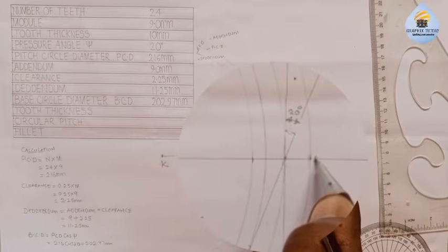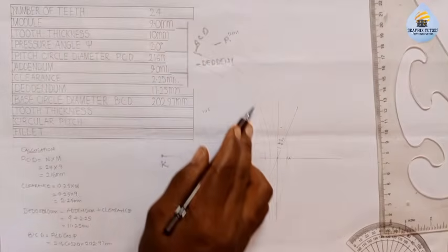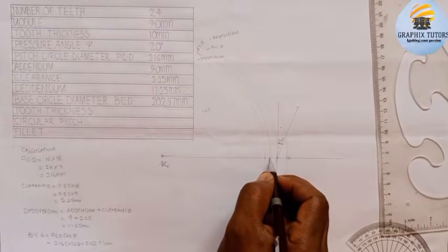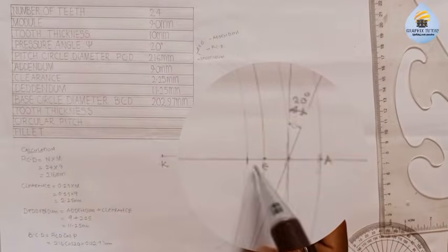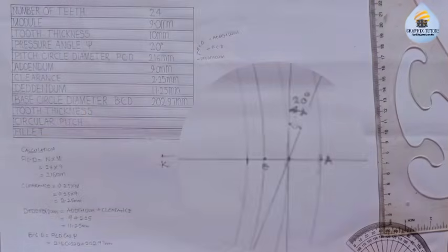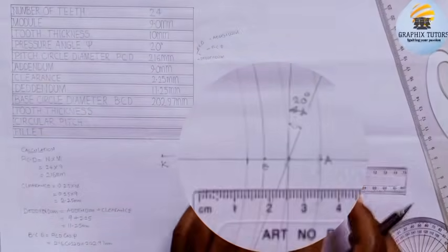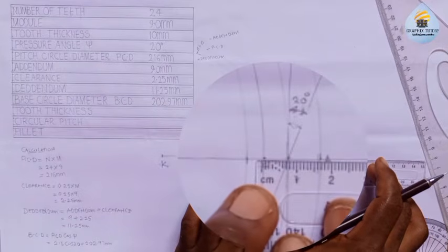This is the addendum, let's say point A. We'll now come to the base circle, look at the line of the base circle here on that horizontal line, and call it point E. Now you look for 1/3 of AE to get point B. So measure AE first.